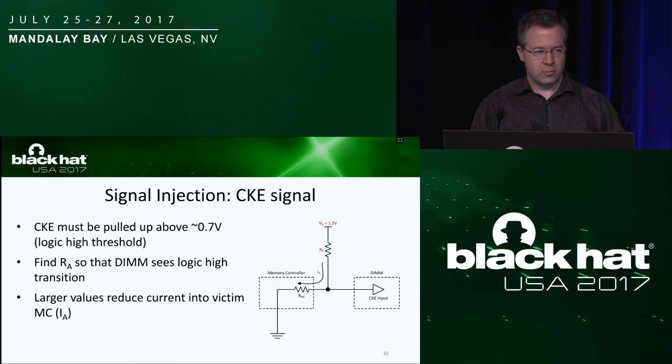So the CKE signal being part of the self-refresh exit, we needed to be able to control that signal to be successful with our attack. So the first thing we did with that was we measured the signal, and we found that it was being tied by the memory controller to a low or ground state.